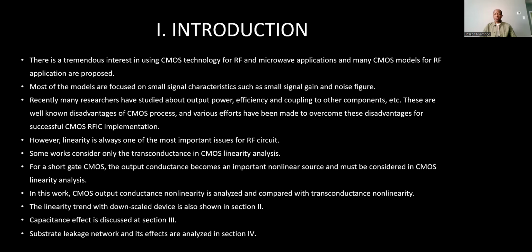However, linearity is always one of the most important issues for RF circuits. Some works consider only the transconductance in CMOS linearity analysis. For a short gate CMOS, the output conductance becomes an important nonlinear source and must be considered in CMOS linearity analysis.